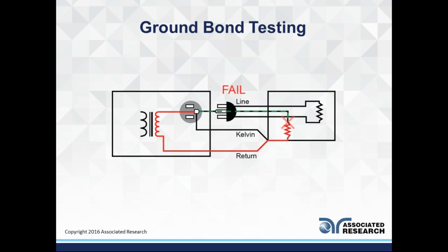Because if you were to start selling these and a fault condition were to occur, and now a lot of current is leaking to your chassis, well, there's way too much resistance on your ground path, so it's going to find another path, usually staying on your chassis waiting for an operator or consumer to touch it. So that's the point of having those limits set and those standards, which we'll get into a little bit more. We'll actually look at a 60601-1 standard where it specifically states how to test your ground circuit.